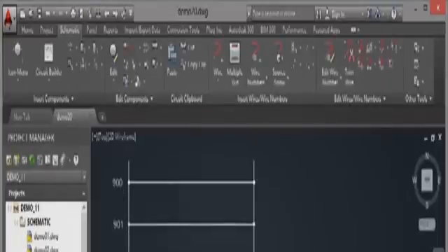Now, I could, if I wanted to, change that to 2, which means it would then go 900, 902, 904, and so on. I don't need to do that, but all that index is the sequential numbering. So it's doing 1 by 1, or 2 by 2, or 3 by 3, and so on. I'm going to click on OK. Just watch your reference numbers down here on your ladder. When I click on OK, drawing updates, regenerates, and I start at 900 instead.